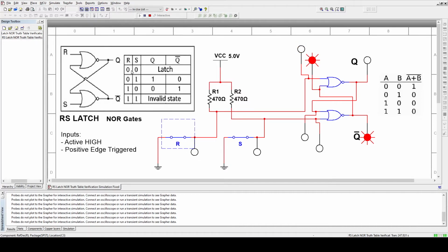Now I'm going to go back to the latched state. I'm going to operate this one now, and we're going to have a momentary set high. So things are going to trigger the Q to be high and the not Q to be 0. And then no matter how many times I'm going to activate that switch, things are going to stay. So it's a latching system. We can latch this onto reset state, pressing and pressing, or we can latch it into set state.